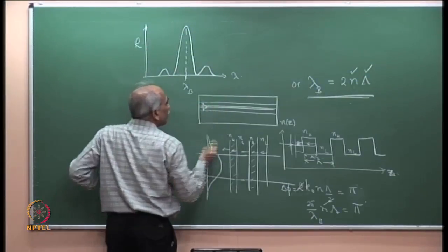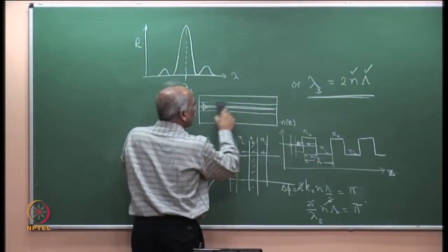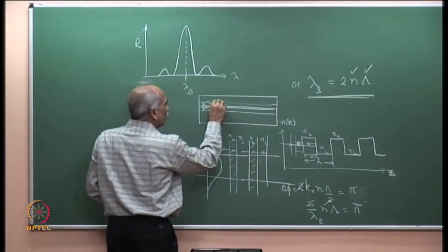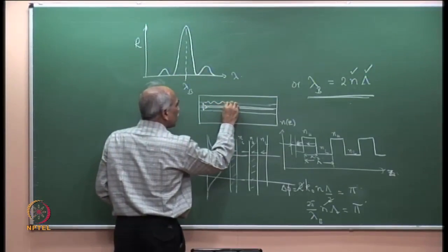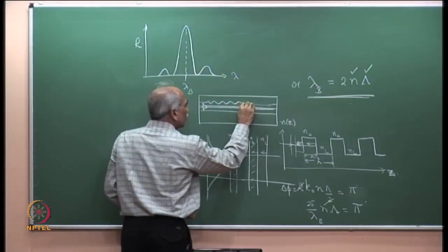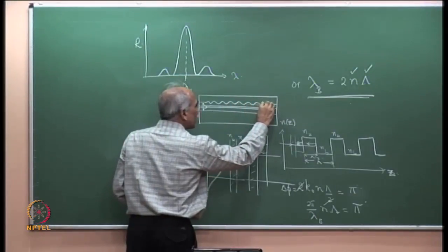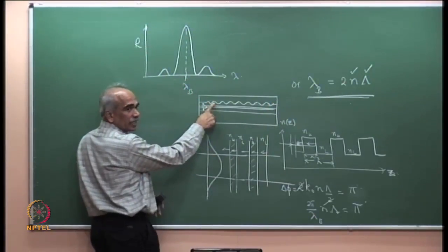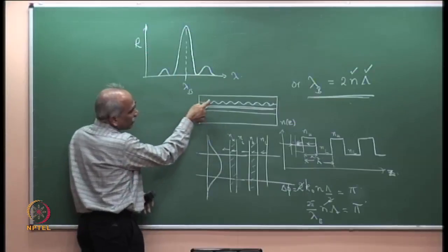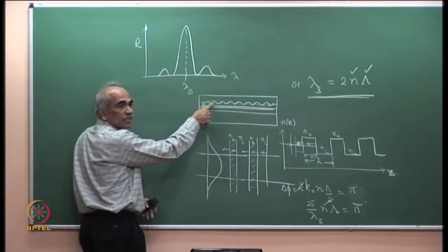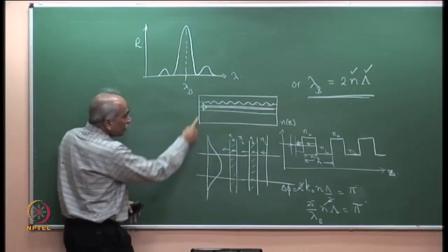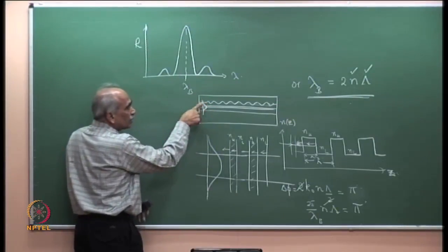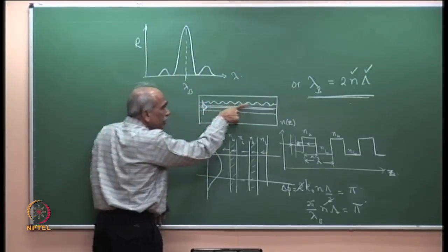And therefore, instead of writing across the whole waveguide, they make corrugations or periodic refractive index variation in the cladding. That is why you see that structure which you saw on the PPT, that you have periodic refractive index variation here, because the materials are different. Please see, this material is different, this material is different here, and therefore, the refractive index here is different, refractive index here is different. And the mode here, please see, this is the mode, guided mode. The tail of the mode sees this periodic structure.